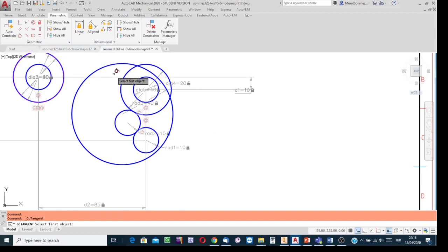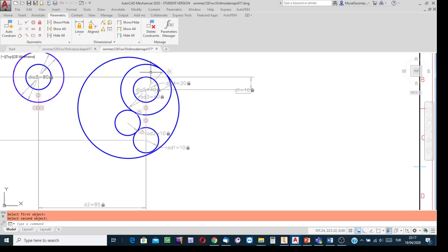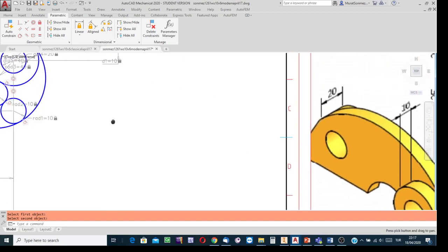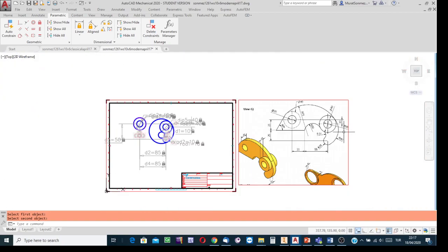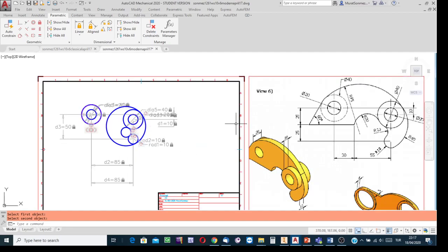Click on this button and then say that this circle and that circle must be tangent. Great. You see, now I managed to have the necessary circle over here, after trimming, to find this boundary. Okay, another circle has two tangent points.